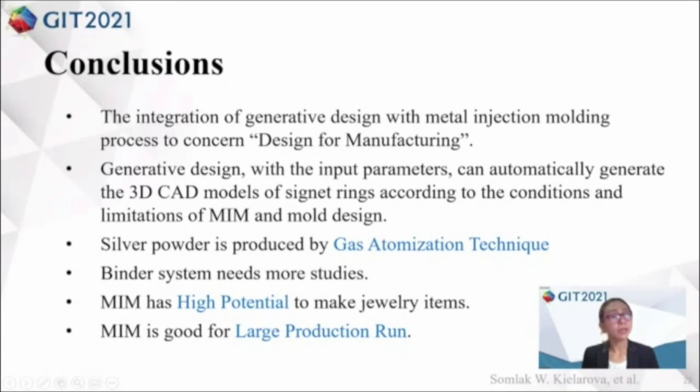Now I would like to bring you to the conclusion part. Here in this research, we integrate generative design with the metal injection molding process to consider design for manufacturing. We take manufacturing conditions into account since the design stage. Generative design with the input parameters can automatically generate a 3D CAD model of signet links according to the conditions and limitations of MIM and mold design.